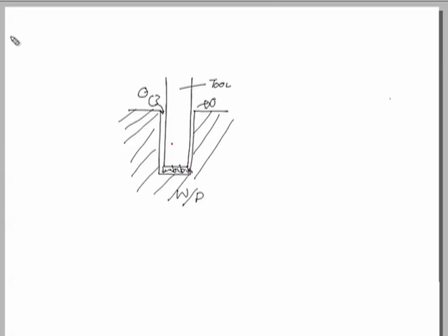Now, if the fresh abrasives cannot reach this zone, then the cutting performance will not be good. Not only should the abrasive reach this position, but it also needs to be flushed out from this position, so that a fresh cutting edge can enter. Therefore, this is an inherent limitation of this process, where very high aspect ratio holes cannot be drilled in an efficient manner.